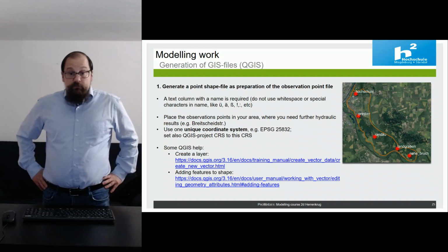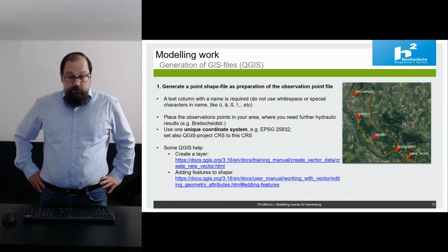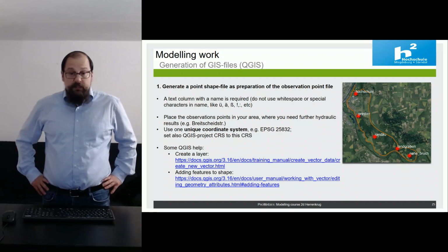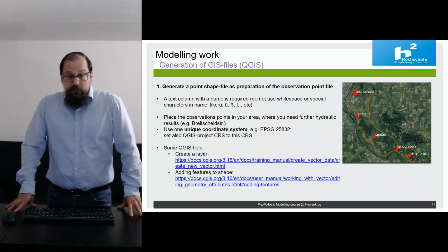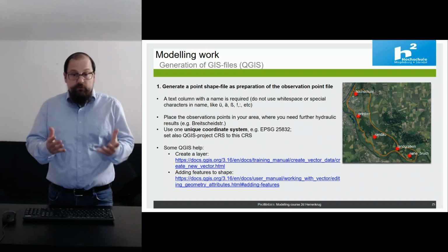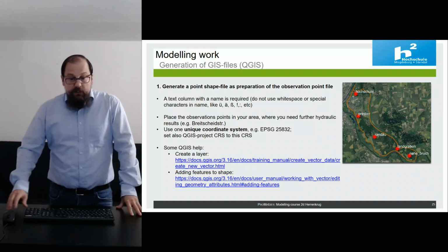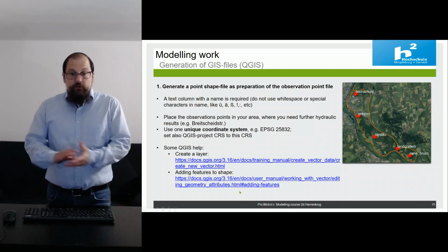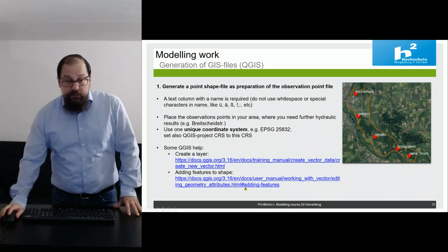Here's some help for QGIS. Just have a look. These are QGIS manual information, for example, how to create a layer. You can create a point shape layer for your observation points, and how you can add any features to your shapefile is also explained here.